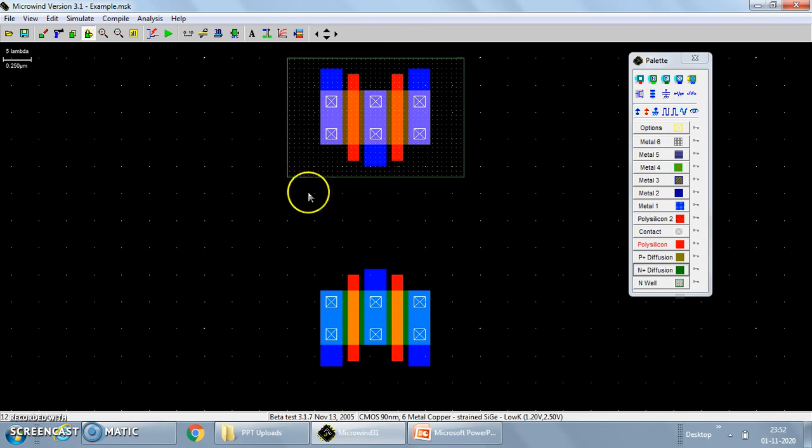See, always P MOSFET is itself designed with N well, but this N well should be provided with VDD so as to work it properly. So I will add here the VDD. So along with that we have seen, so if these are the two P MOSFETs, I will call this as a source, gate and drain. Source, gate and again drain. Or we can call interchangingly, we can give labels to these terminals as per our convenience. So right now I will call this as a source, this as a gate and this as a drain for the first transistor. And this is again drain, this is a gate and this is a source.